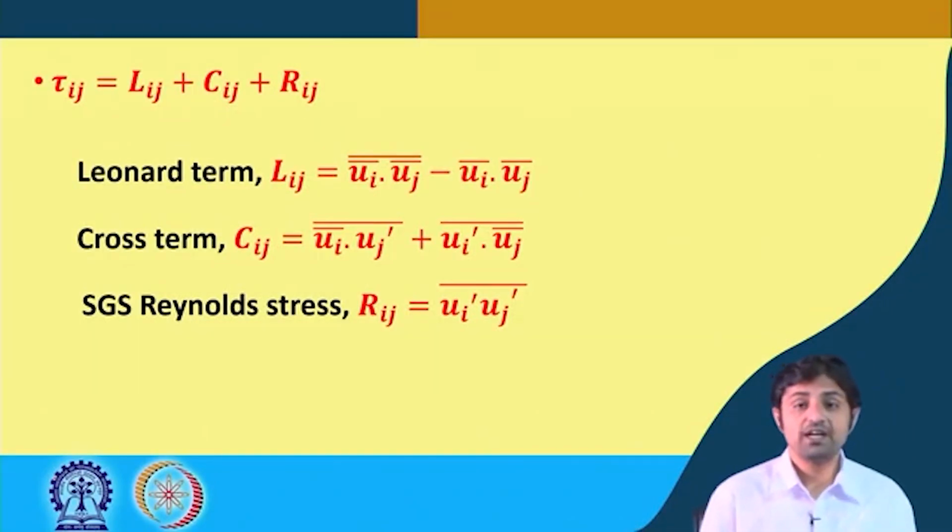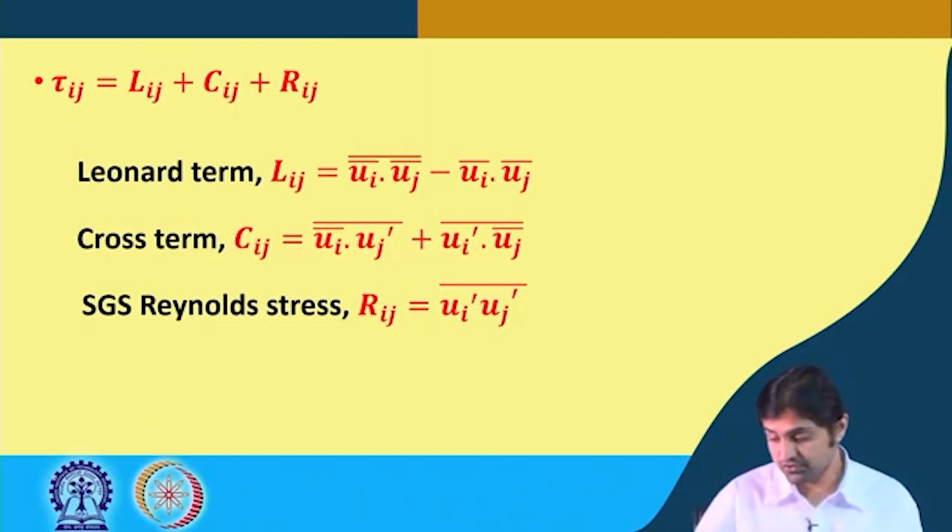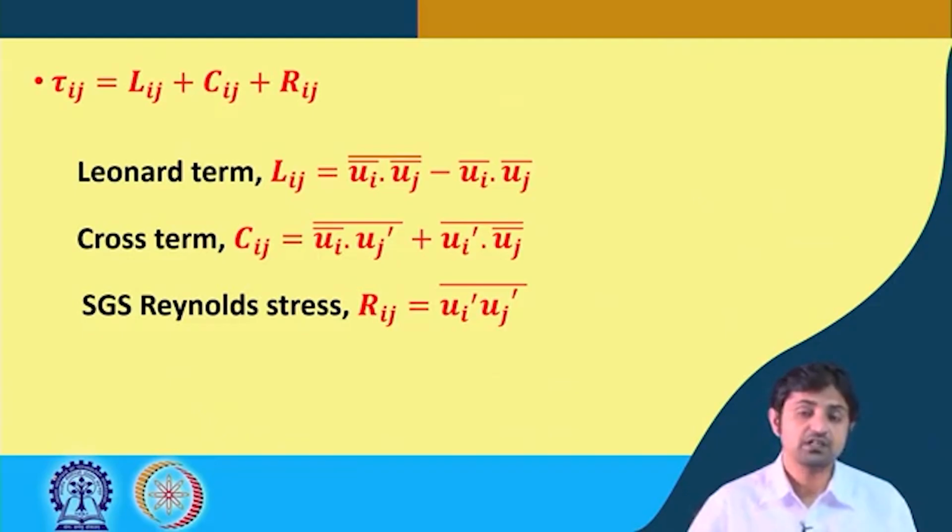So this gives you an overall idea of the differences. We have covered Reynolds shear stress in a little more detail. The idea of DNS, why it is computationally so expensive, has been introduced. We went through terms like Re to the power 3/4, and the number of grid points being equal to Re to the power 9/4. The basic idea of LES is that we use the filtering function to model the large eddies, whereas subgrid scale modeling is used to model the smaller eddies. So information like the different terms, the Leonard term, cross term, SGS Reynolds stresses and things like that, have been covered in the turbulence modeling part. Many complex equations are not supposed to be remembered by you, but an overall idea about those equations is whatever is required in this particular module.